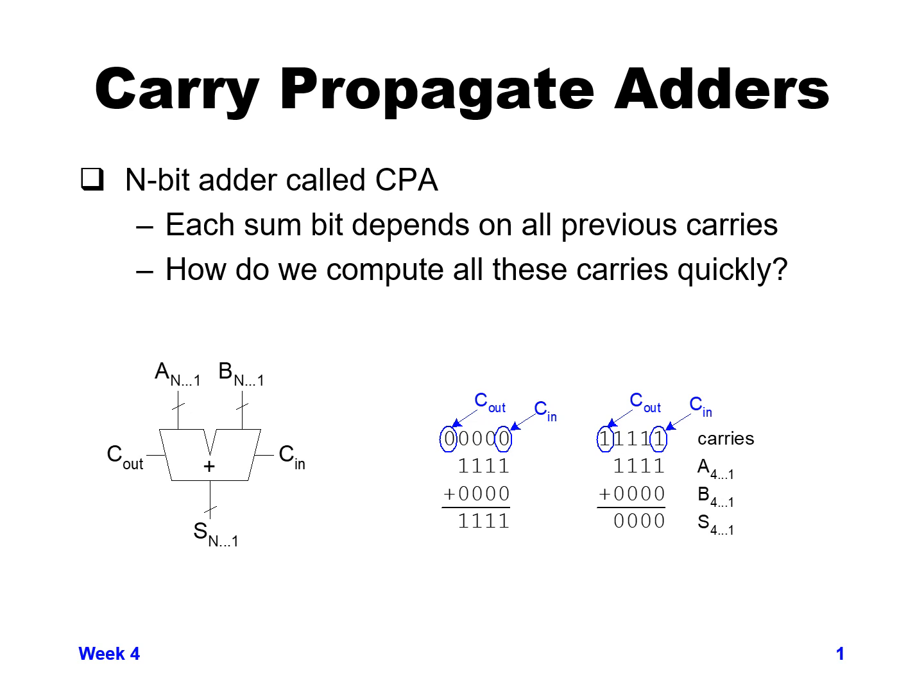On the right-hand side is an example of a 4-bit adder adding the number 1111 to the number 0000. Depending on your carry in, if you have a carry in of 0, you just get four ones out. If you have a carry in of 1, then each bit gives you a sum of 0 and a carry of 1 going to the next bit, and then 1 plus 1 gives a 0 sum out with a carry going to the next bit. You can see that the carry has to propagate through every single bit in this particular case.